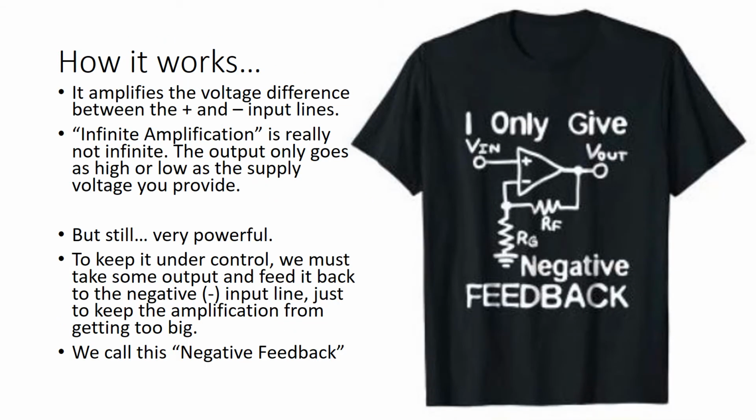So how does it work? It amplifies the difference between the plus and minus input lines. So sometimes we call it a differential amplifier. So infinite amplification is really not infinite. The output can only go as high or as low as the supply voltage that you provide. And I'll show you how to provide that supply voltage when we do the lab. But still, the amplifier is very, very powerful.